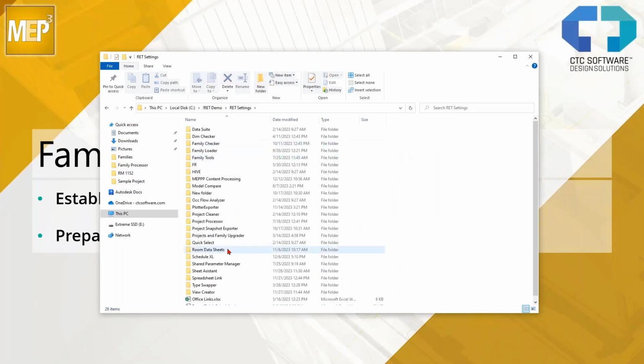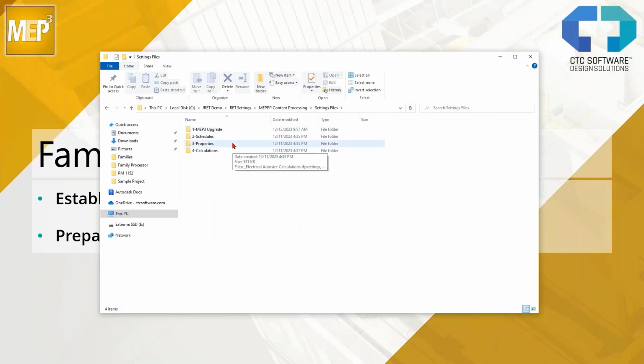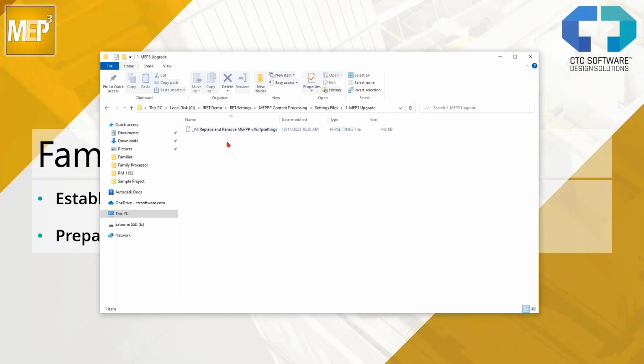So in my settings folder here, I have my content processing folder and my settings files, and I've broken it up into 4 sections here. Section A, or 1, is the upgrade settings file. It's one file that if you are going to upgrade your MEP content from a previous version, you're going to run this on all of those families.